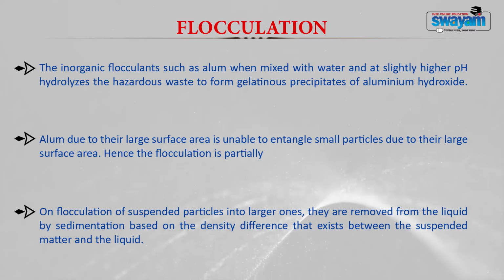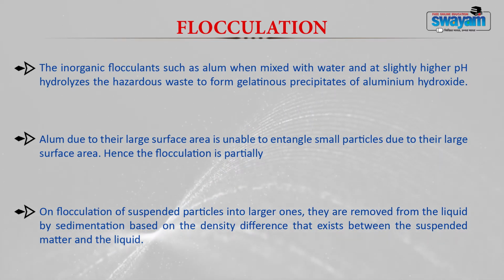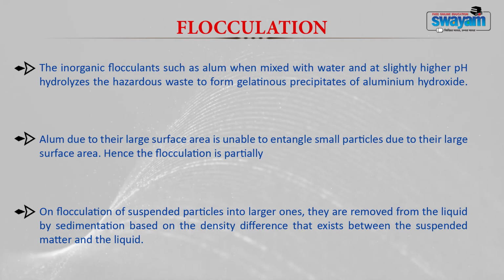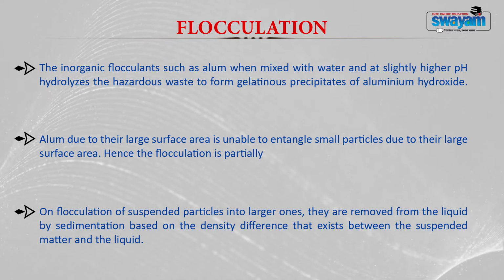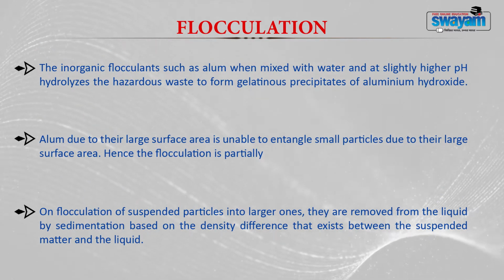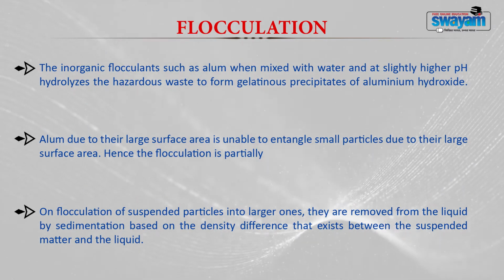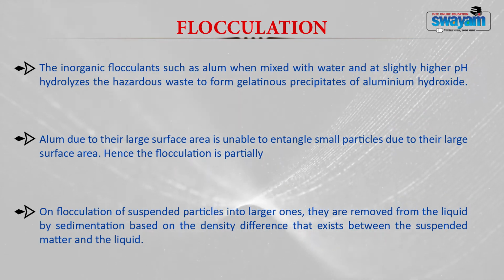Now, on flocculation of these suspended particles into larger ones, you allow them to settle down, and the suspended particles which are flocculated will be removed by the sedimentation process. Generally, the separation takes place based on the density difference that exists between the suspended matter and the liquid.